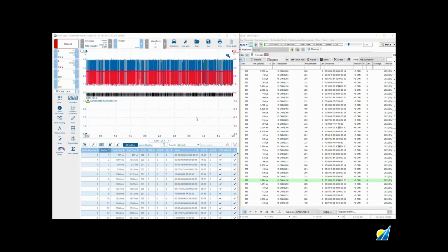We're not worried about CAN fault here, just CAN data with the ABS ECU offline. Be careful when you do this, because if you disconnect an ECU with a termination resistor inside, you are going to change the impedance of the network. So you may have to insert a 120 ohm resistor. As it so happens, that doesn't occur when you disconnect the ABS ECU on this vehicle.